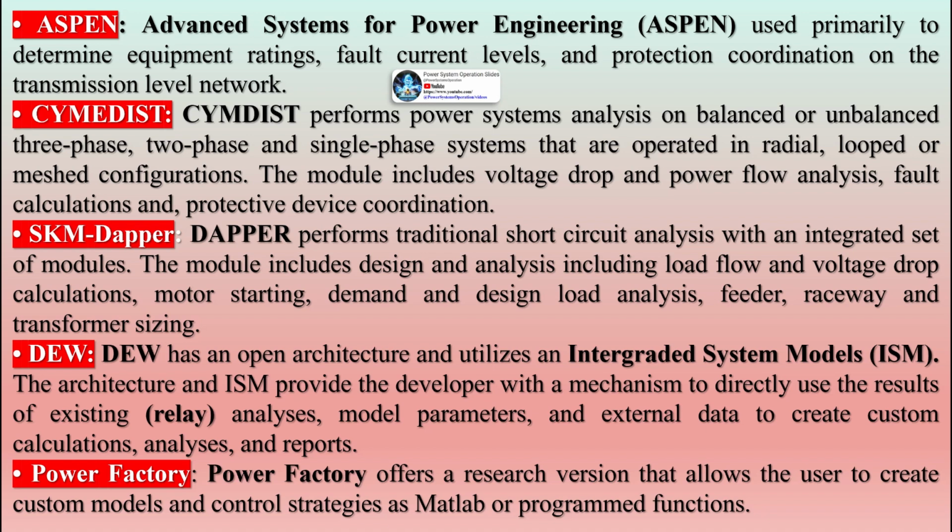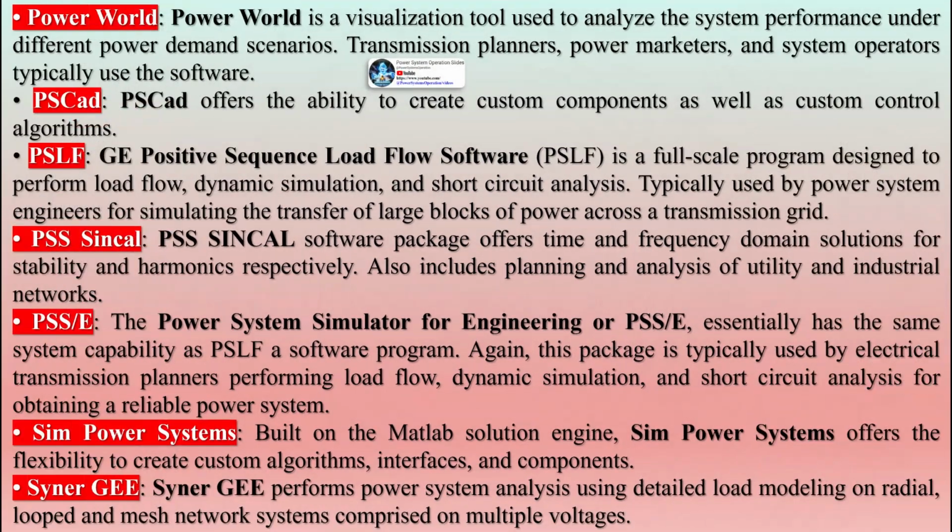To get enough information, different types of faults are simulated at different locations and the study is repeated. Normally in the short-circuit analysis, all the shunt parameters like loads and line charging admittances are neglected. Then the linear network that has to be solved comprises the transmission network, generator system and fault. By properly combining the representations of these components, we can solve the short-circuit problem.